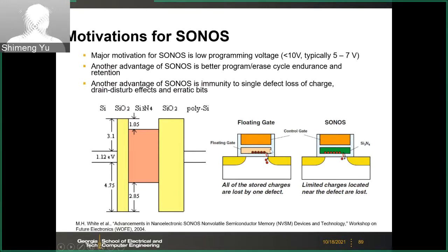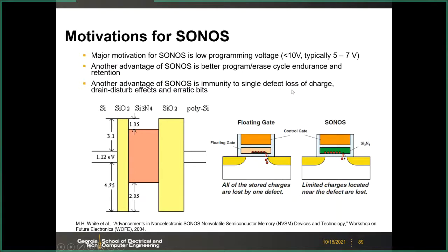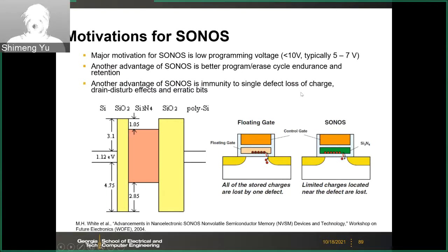One key difference is that in this kind of charge trapping mechanism, if there is a loss of the charge, it will be local. So what does this mean? In the floating gate transistor, as we discussed before, if you have some leakage path here, for example, somehow in this part, the electrons in the floating gate, this is polysilicon, which is conductive, so the electrons may move around. So if you leak one electron, all the electrons may follow this path. Then your data retention may be poor.